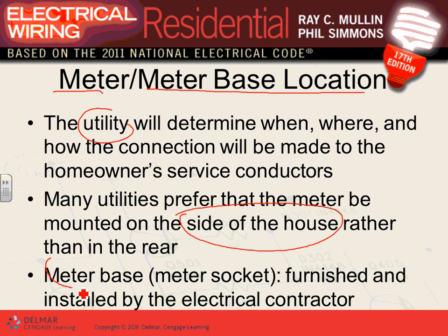The meter base, the meter socket, is always specified by the electrical utilities, designed by the engineers, and installed by electrical contractors. The meter socket, the box that houses the meter, has utility specifications. For example, Xcel requires you for dwellings to install a meter socket rated for 200 amps, regardless of what your service is. Then they bring the meter and put it inside it, but you will buy that meter socket, design it, and install it.